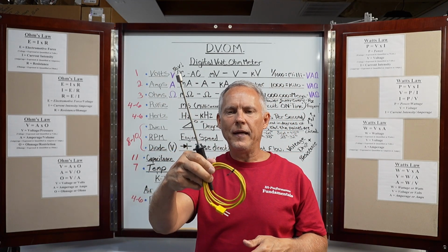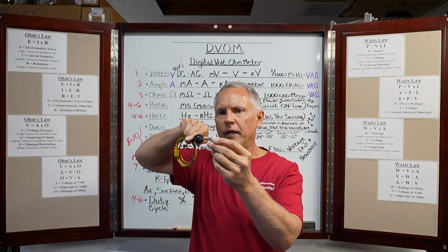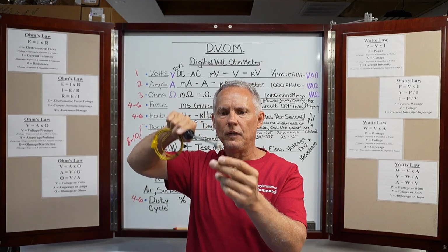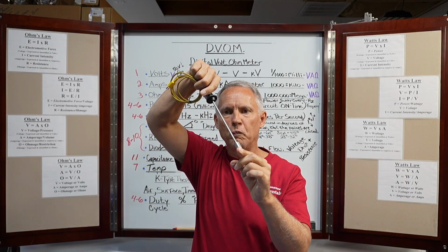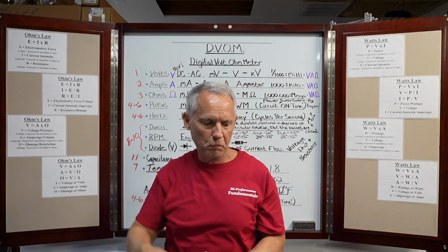This is a surface probe. Also a K-type thermocouple, but a surface probe. It has two little contacts right here. Make sure the surface itself is clean. Touch the two contacts to your surface, they're spring-loaded. Wait, and you get a reading value. Now you know what the surface temperature is, plain and simple.